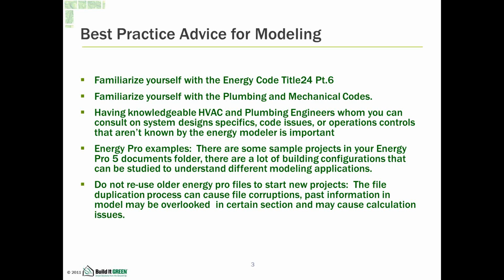I don't really want to call them templates. They're just something you can look at to give you an example of how to build systems out. So if you open up your Energy Pro 5 folder in your My Documents, there should be a library with an assorted style, a bunch of different models with different applications, whether it be high-rise, low-rise, single-family, commercial buildings. Each of these examples show great breakouts of how to design some of these plants and HVAC systems. So that's always a good idea if you don't have someone you can call to figure out how to model a certain system.